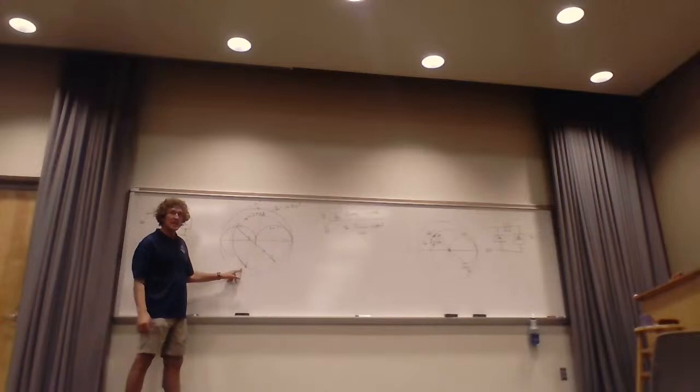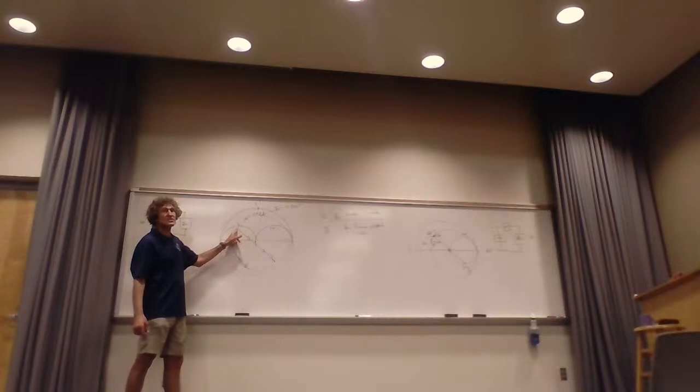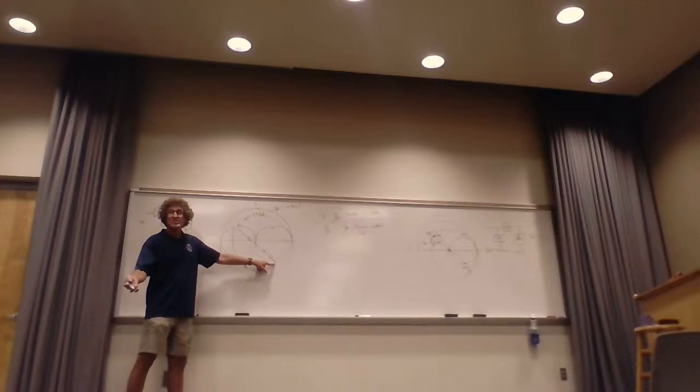Now when you're here, the key is this. If you're in the admittance domain, I can get to this point or this point, correct? But if I wanted an inductor in series, I'd want to go to this point. And the reason is because this is something plus j something. When I go here, I get 1. If I'm going to get on a 1 circle here, 1 minus j something. If it's an impedance, I'm adding a plus j, which is an inductor.